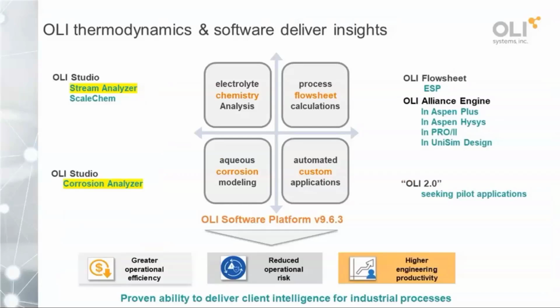So when we think of software in our offerings, we look at that generally in 4 quadrants, if you will. So we start with the chemistry. That will be one focus, especially of the first day today, is to look at electrolyte chemistry, and that happens in the OLI Studio. So Stream Analyzer you can think of as a virtual laboratory on your desktop. So if you want to study changes in pH or temperature and pressure and how that affects the system that you're analyzing, that's where we want to start. It's also the easiest way to kind of understand how we work with data input and then how that changes.